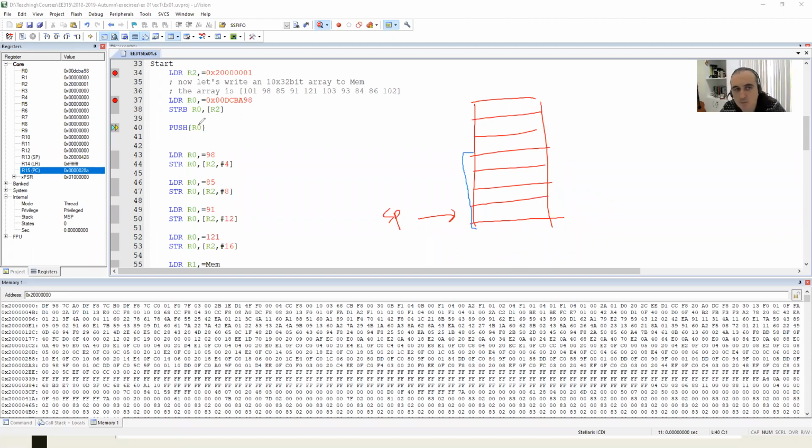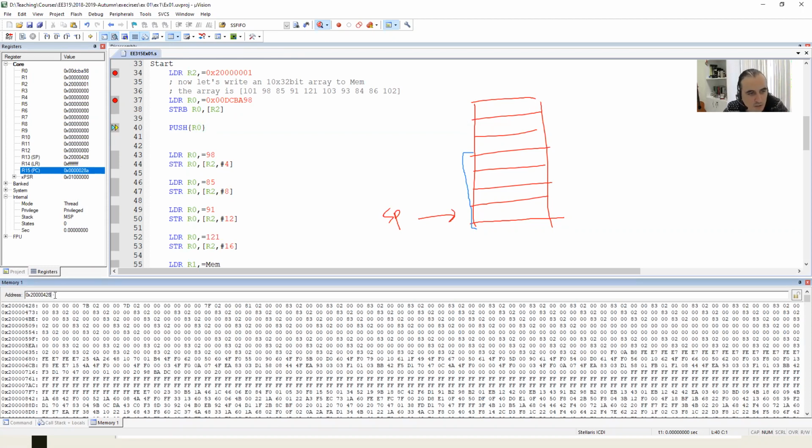The value will be written somewhere in the memory where the stack pointer points, right? Where does the stack pointer point to? Do you have any idea? Can anybody see it on the screen? I'm moving my cursor there. This is the stack pointer. Actually, that's a place in the memory. So let me look at that place in the memory, guys. I'm writing the exact same value here. So it is the start of my stack memory. This is this value, this value, this value, and this value.